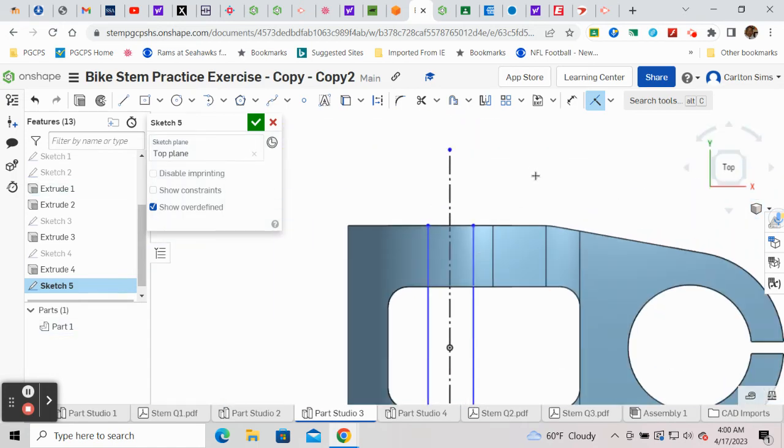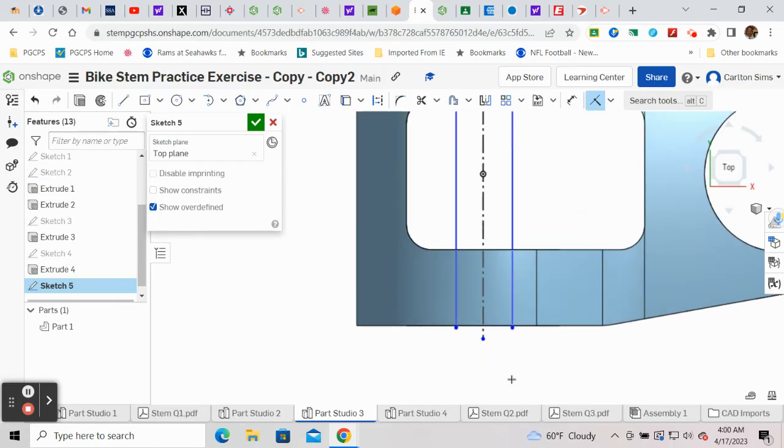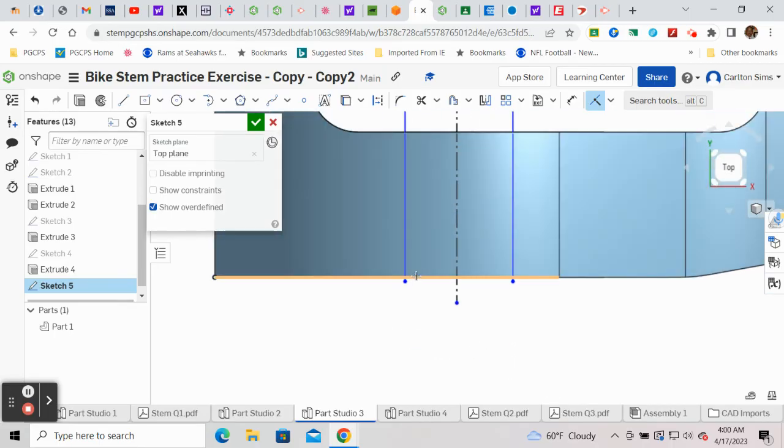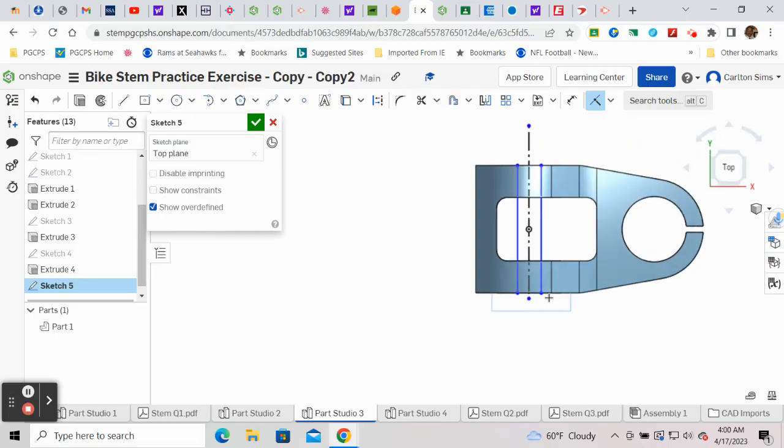Okay, I'm going to go down the bottom and check just to make sure these are the same. I want these to be coincident with the line. Okay, so I'm going to that point to the line, and you see that one automatically. Okay, so I got those. I'm going to deselect the coincident constraint. I'm going to get my line tool again, guys.